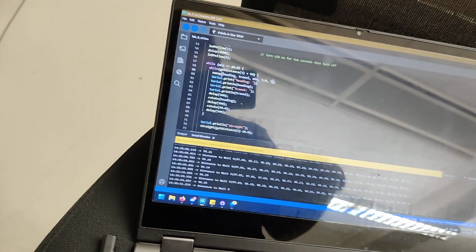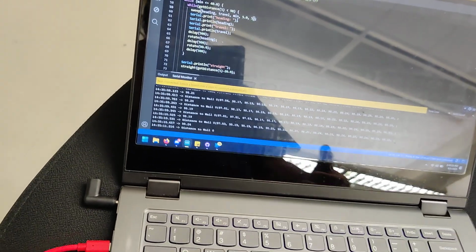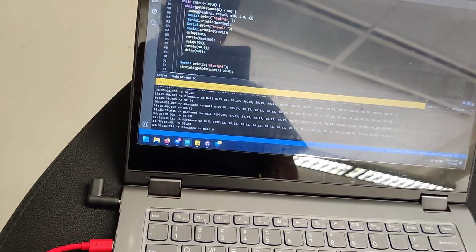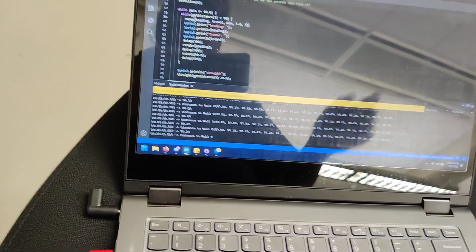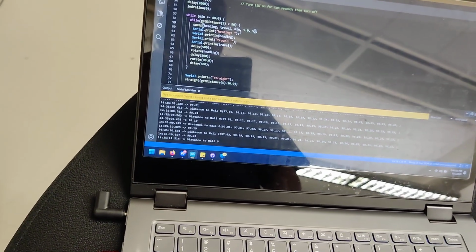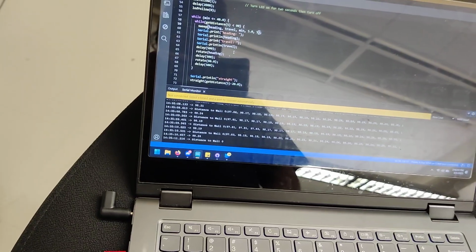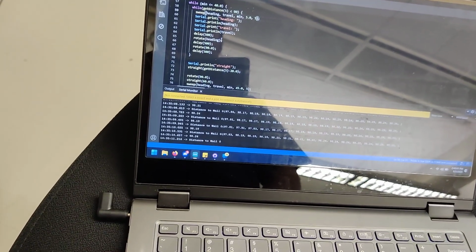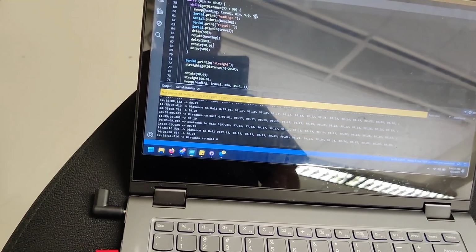If not, that's fine also, but it should be one of the side walls. Debug stuff, it's going to rotate towards the direction of that closest thing. Within sweep, min gets assigned to our heading. Once it's there, it's going to rotate 90 from that. So our ideal case is if it's facing this top wall, it's going to face directly towards it because it's going to be the closest thing to the ultrasonic sensor. It's going to rotate 90 facing our exit.